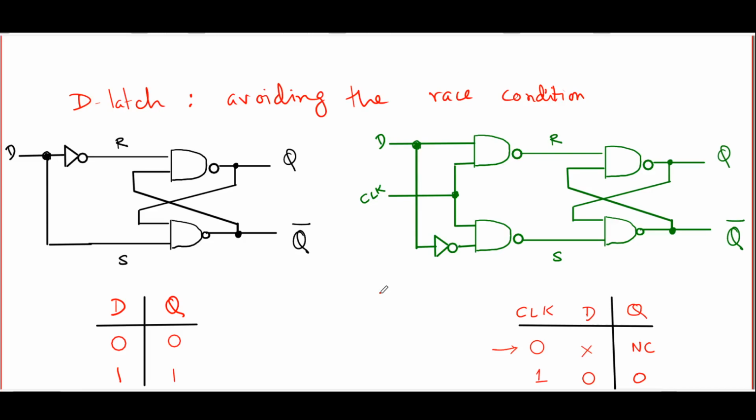So, there seems to be no effect of a sequential circuit here. The feedback of Q and Q bar to the two intermediate NAND gates doesn't really have any effect. And frankly, it looks like this circuit does nothing whatsoever. You could have achieved the same thing just by using a simple wire joining D and Q and a NOT gate between D and Q bar. What makes a D latch actually useful is that you can clock it, and the clocked version is what we are going to discuss next.